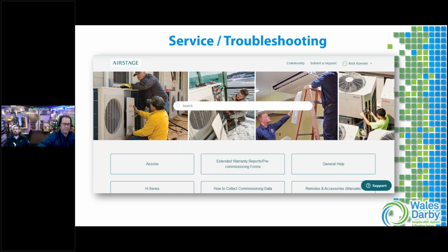We see a lot more applications. Again, we're trying to save space outside, so that's kind of my go-to when I get these multiple, let's call them 2 air handlers in one space. Well, instead of putting in 2 single zone systems, I can put a J series, like I said before in a rebate binder, that there was a 5-ton outdoor unit that I can put multiple indoor units on. So if I can do 2 air handlers there and split it up to other systems, right? The J series might be a good thing for you.